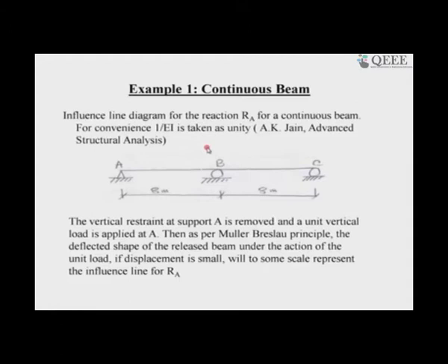I will also tell you later that for statically indeterminate trusses or highly statically indeterminate structures, the advantage of using the Muller-Breslau principle may die out, because if you remove one redundant and try to examine the displaced shape, the other redundants will prevent it from displacing well, where the shape of the curve would otherwise be apparent. So there is a disadvantage theoretically, and in the experimental determination of influence line diagrams.